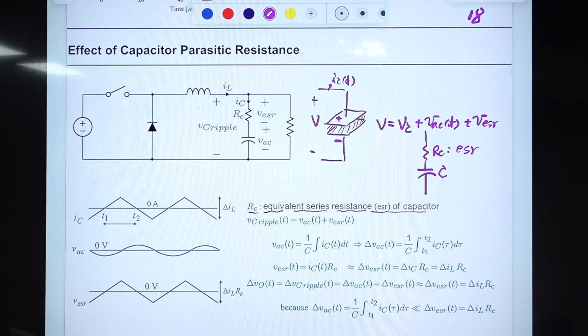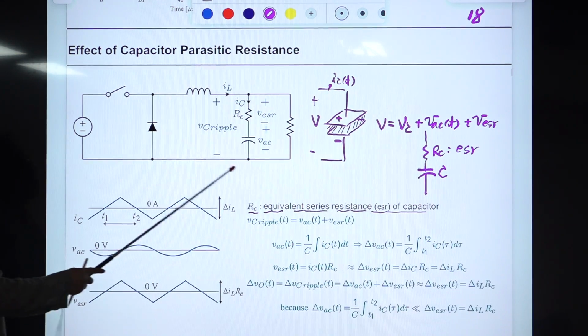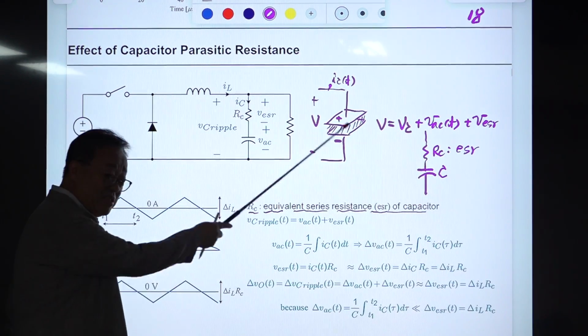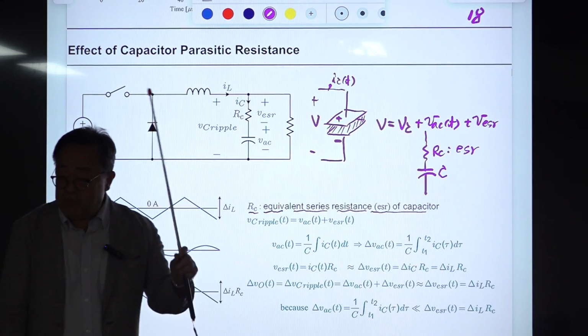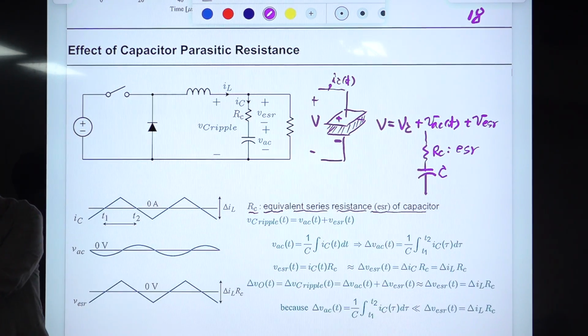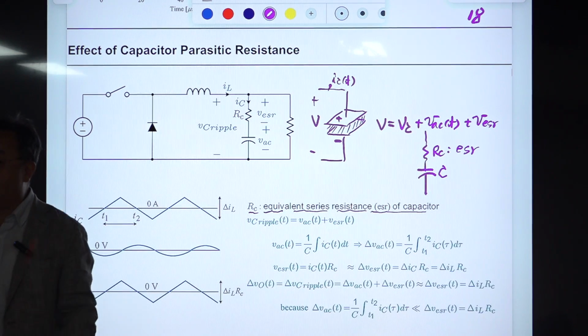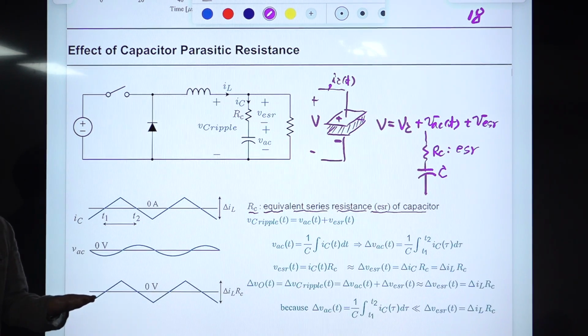They make this mistake because they think they are using the capacitor with very small ESR. Then that 0 is moving to the higher frequency. Then within the bandwidth, the ESR 0 is nothing. After it appears beyond the loop gain crossover frequency, that phase boosting effect is just wasted, and the converter becomes unstable, right?